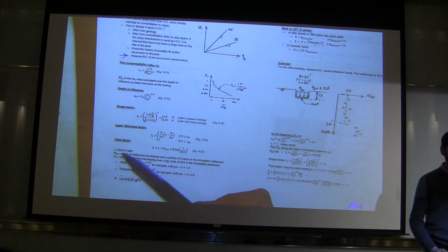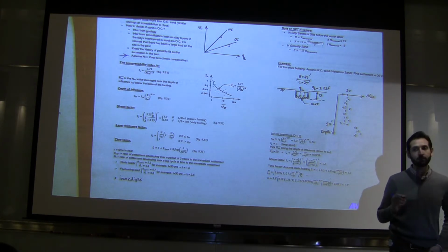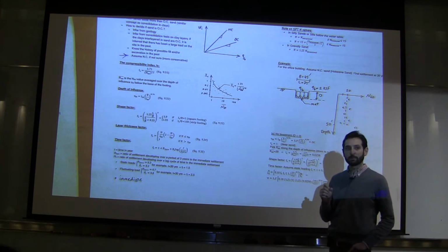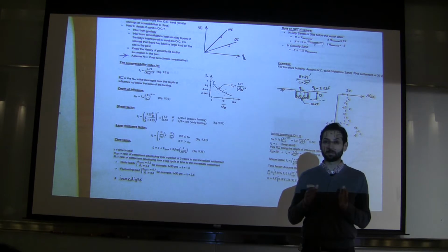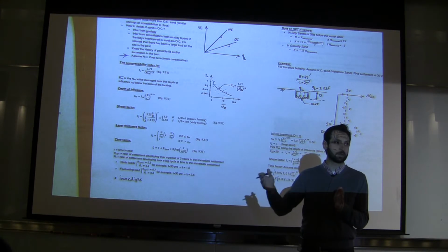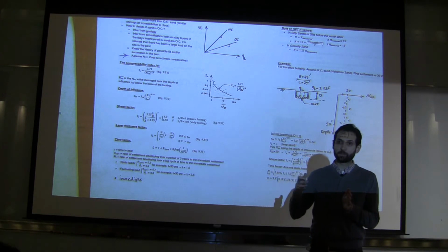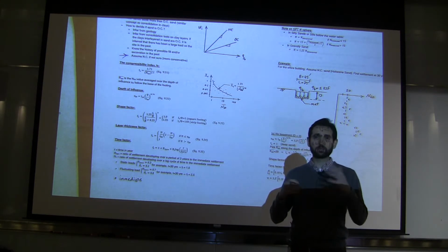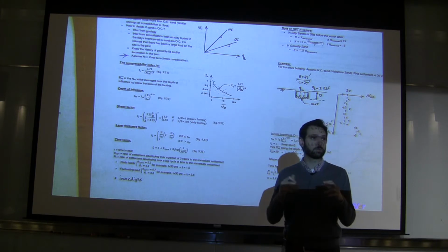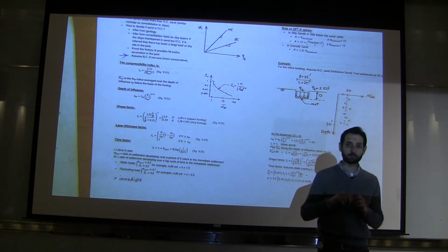And then we get to the time factor. It turns out that even if you're in sand, you get a little bit of consolidation type settlement, which means over time you get this extra settlement due to creep and a little bit of consolidation and a lot of different factors that we just lump into this term called time factor.